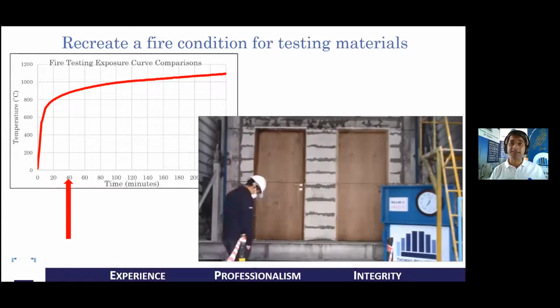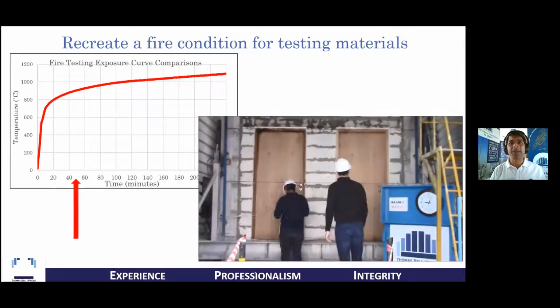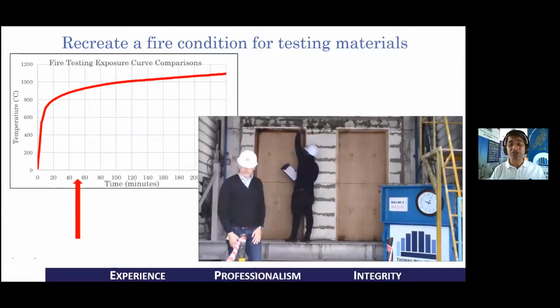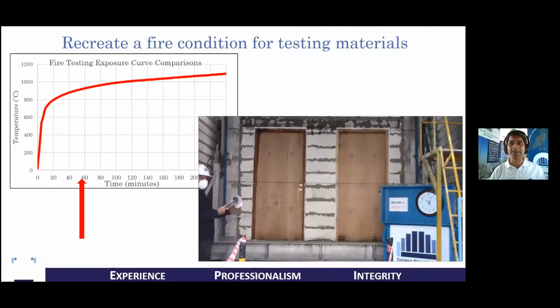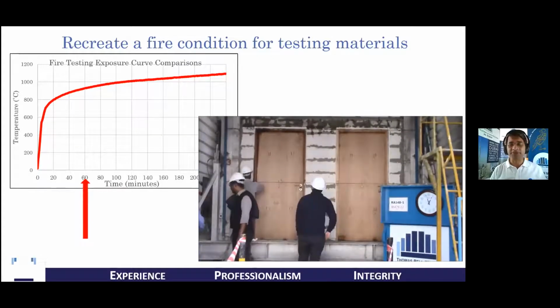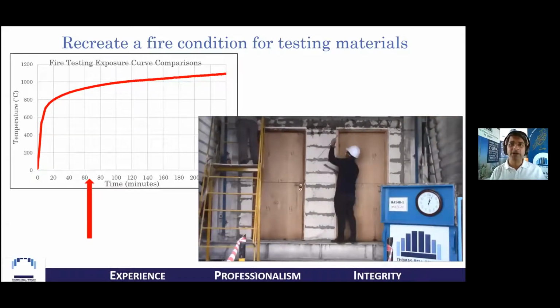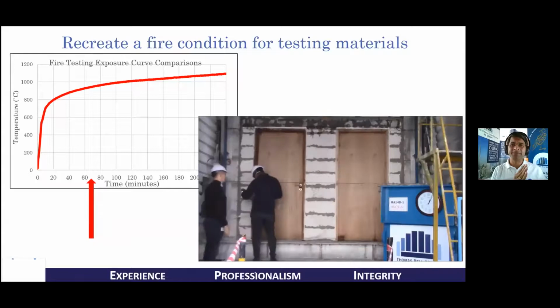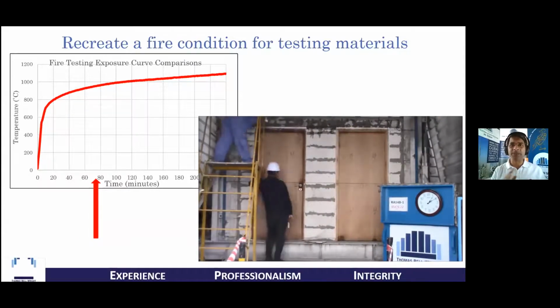These fire resistance tests can often run for up to 3 hours or even 4 hours, depending on what we are testing, as well as depending on the regulation that exists in that geography where that is being demanded. As you can see, there is a graph running on the left when the pointer is showing how, with respect to time, the temperature inside the furnace has been increasing.